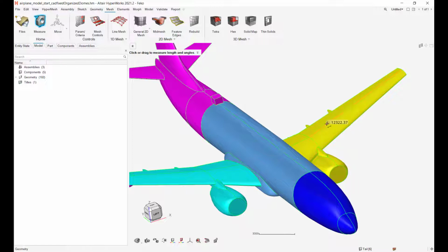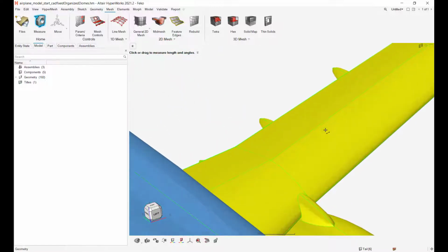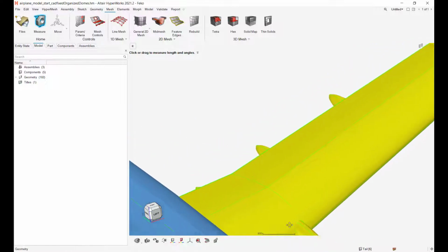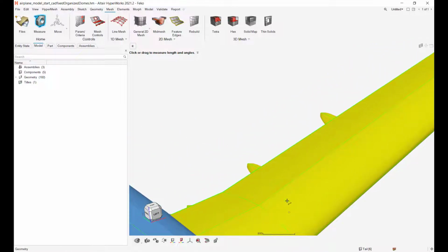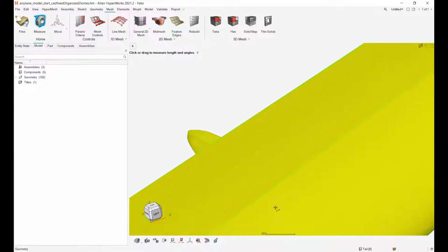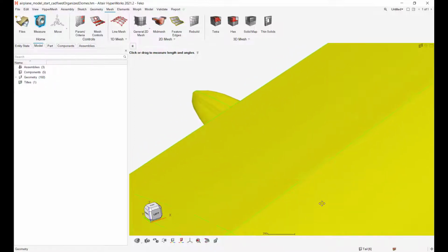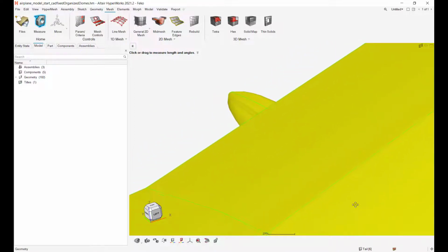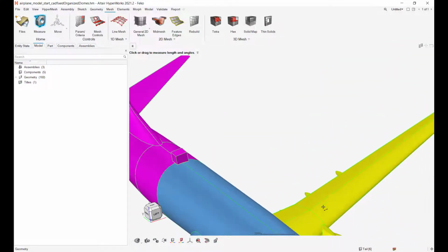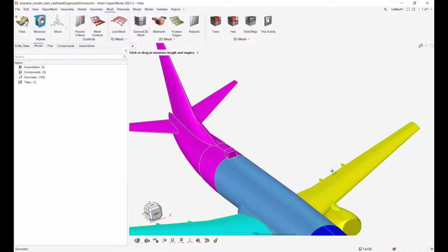Okay, so probably a mesh size of, I sometimes like to use this little thing at the bottom. It gives you an idea. Maybe a mesh size of like 200 should be a pretty decent mesh size. Just kind of line that up and see what 200 is going to look like. It's going to be decently coarse, but it's going to be fine enough.